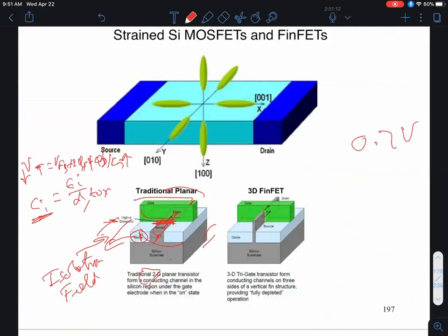All right, so going back to this figure over here, the reason you get electrical isolation is here, you see that the oxide thickness is very, very large, meaning that the capacitance of a parasitic transistor in this part would be very, very low, the gate capacitance. In other words, the VT would be very, very large. So the VT over here may be 20 volts, while the VT over here is 0.6 volts, okay? That's how, if I have a 5 volt power supply, for example, these parts of the semiconductor will never turn on, right? And that's how you guarantee electrical isolation of this transistor from neighboring transistors.